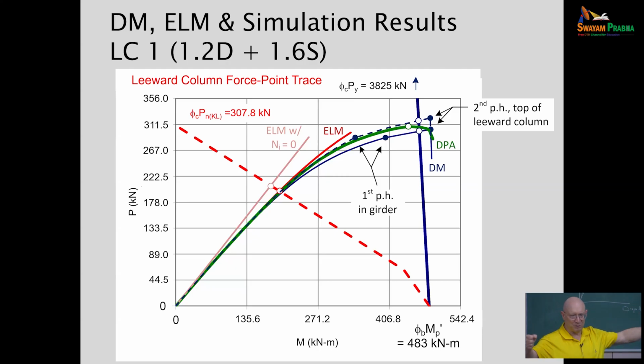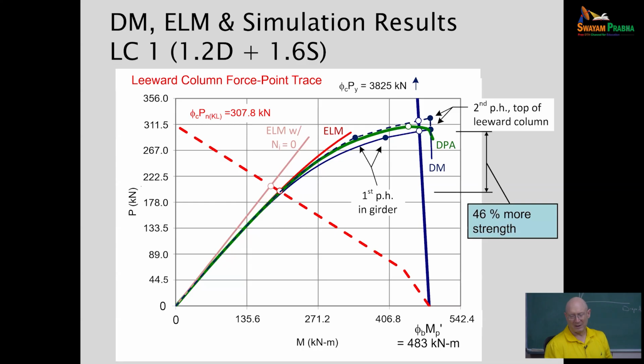Because we have two exterior columns that are providing the lateral load resistance. We have 4 interior columns that are carrying a lot of the vertical load. Those are not helping at all. In fact, when we deflect laterally, we get P delta effects that are destabilizing the rest of the frame. So in a buckling solution, that causes the effective length factor to get large on the exterior columns. Make sense?